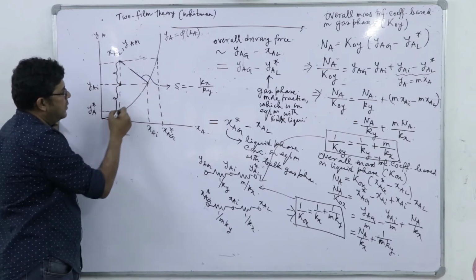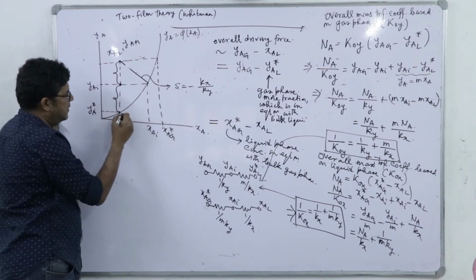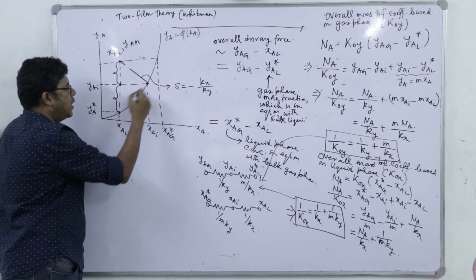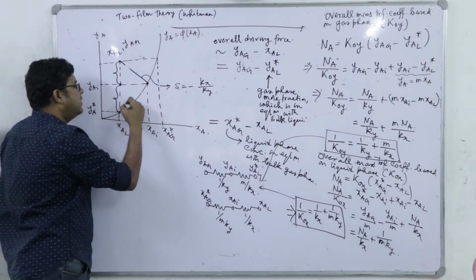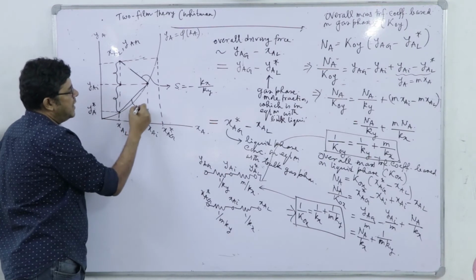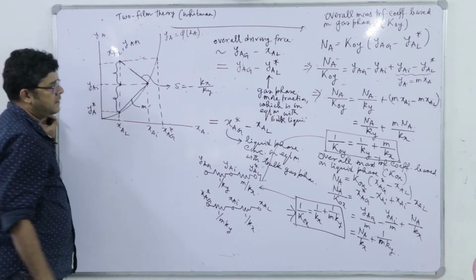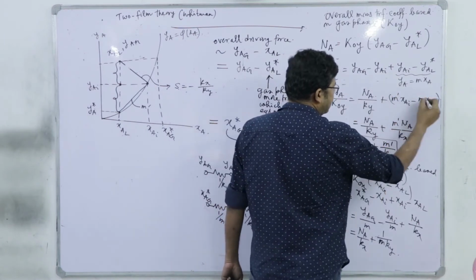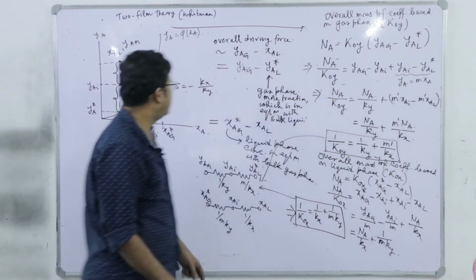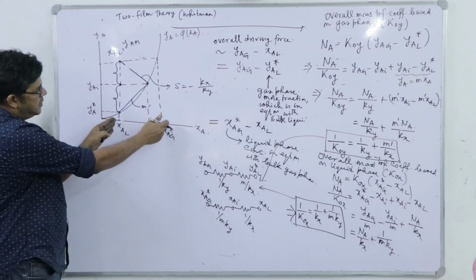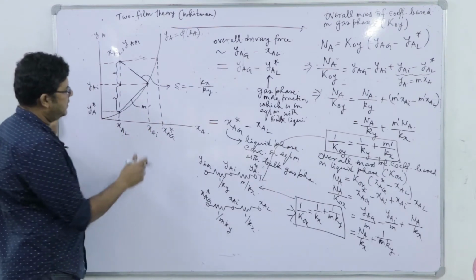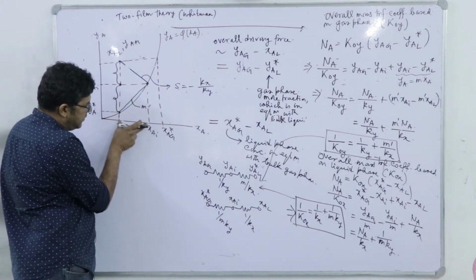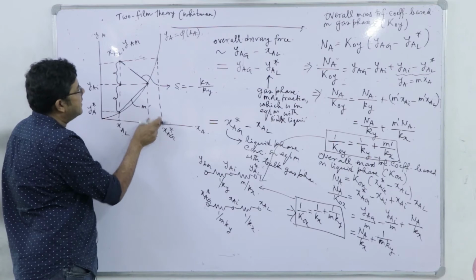So, we are looking over this segment of this equilibrium line, and we have 2 points only. So, if I join these 2 points, I will get a slope say m prime. So, truly this relation will be m prime Kx. On the other hand, when we are looking for this sort of driving force, and we are breaking it down into two, this is the liquid phase actual, this is the gas phase hypothetical.